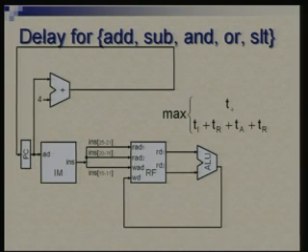The reason why I want to keep T plus in the picture is that, since ALU time is getting summed with other things, I will have to attempt to make this ALU very fast, otherwise things will be bad. So typically in the ALU I will put carry look-ahead logic and stuff like that, whereas the other adder has much more room, much more cushion.